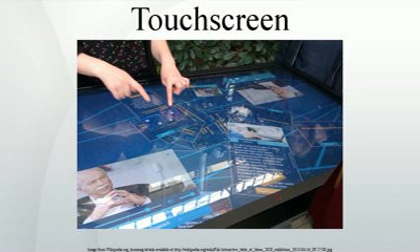Optical imaging. Optical touchscreens are a relatively modern development in touchscreen technology, in which two or more image sensors are placed around the edges, mostly the corners, of the screen. Infrared backlights are placed in the camera's field of view on the other side of the screen. A touch shows up as a shadow, and each pair of cameras can then be triangulated to locate the touch or even measure the size of the touching object, see visual hull. This technology is growing in popularity, due to its scalability, versatility, and affordability, especially for big units.